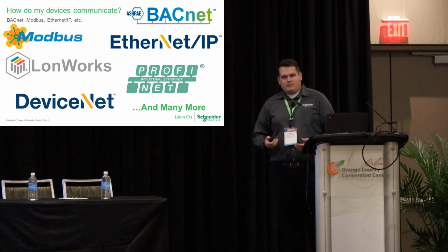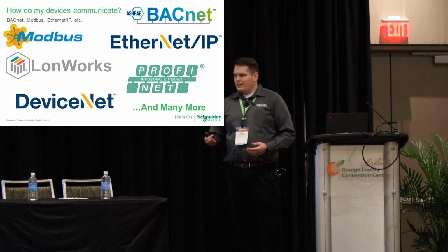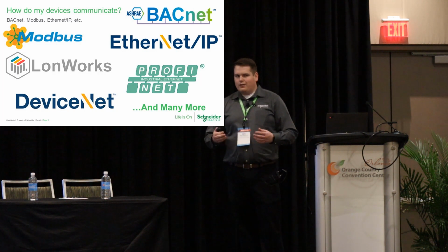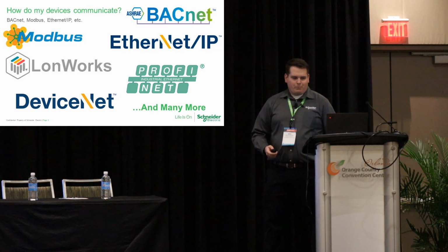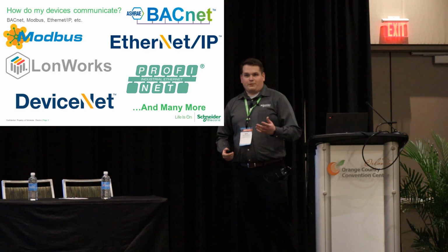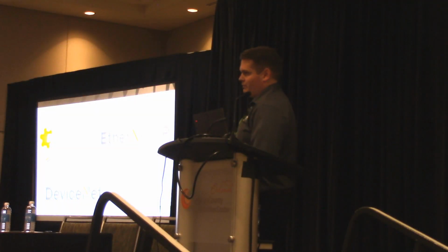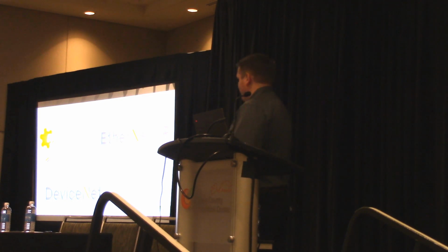Ethernet IP is the kind of Allen Bradley standard. It's managed by the ODVA compliance group. DeviceNet is very similar to that, not identical, but they are very, very similar in the way they function. They're based more off input-output tables, whereas Modbus is based on registers for each device or for each parameter. So your set point, PV, output, PID status, all that is given an address in Modbus. Ethernet IP, you assign that to a table, put it into that table, and the devices communicate based on those tables. They talk back and forth.